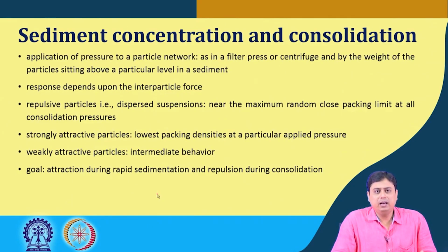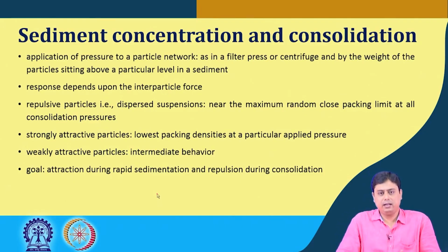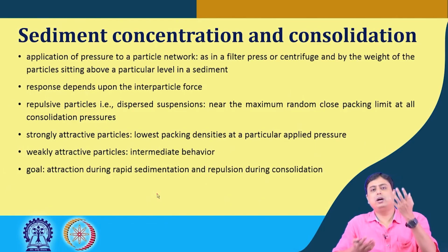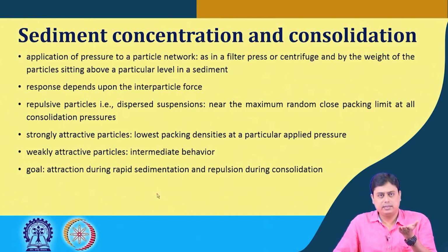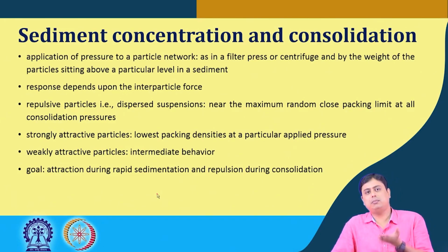So, what can be done? The application of pressure to the particle network in order to compress it, like in a filter press or a centrifuge, or by putting a weight on the top of the sediment. The response to this application of pressure depends on the interparticle force.